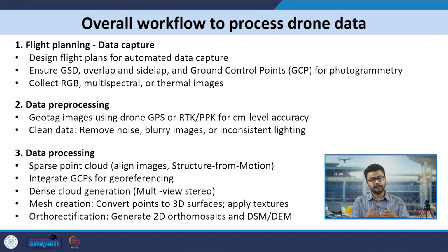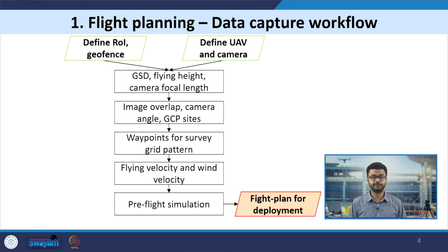So let's look at the software which we can use in these different stages, what are the open source software and what are the commercial software available to help us perform these processings. Let's look at the first stage, which is flight planning and data capture workflow. Here we need to define the region of interest as well as the geofence. At the same time, we also need to define what UAV we have with us and what camera parameters are available.